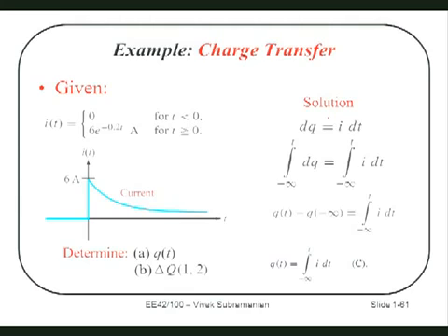Okay, before we get going, let's look at some specific points. At time 0, or let's call it at time 0 plus, just barely past 0, what is the current? It's 6 amps. I take 6 e to the minus 0.2 t, I'll put in t is equal to 0, and e to the 0 is, of course, 1, so we get 6.